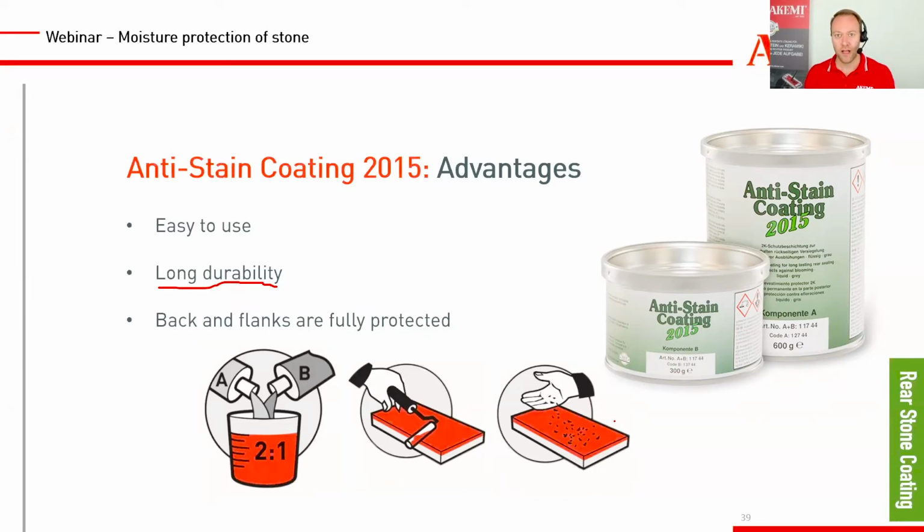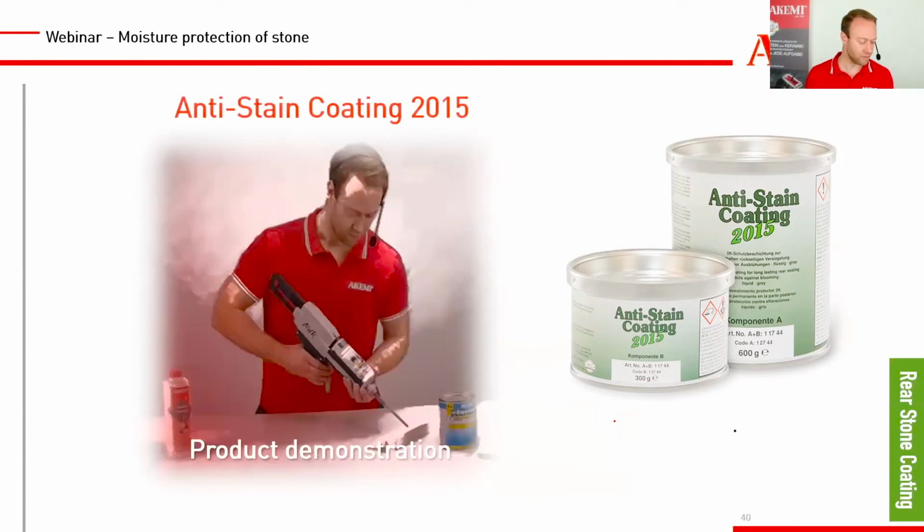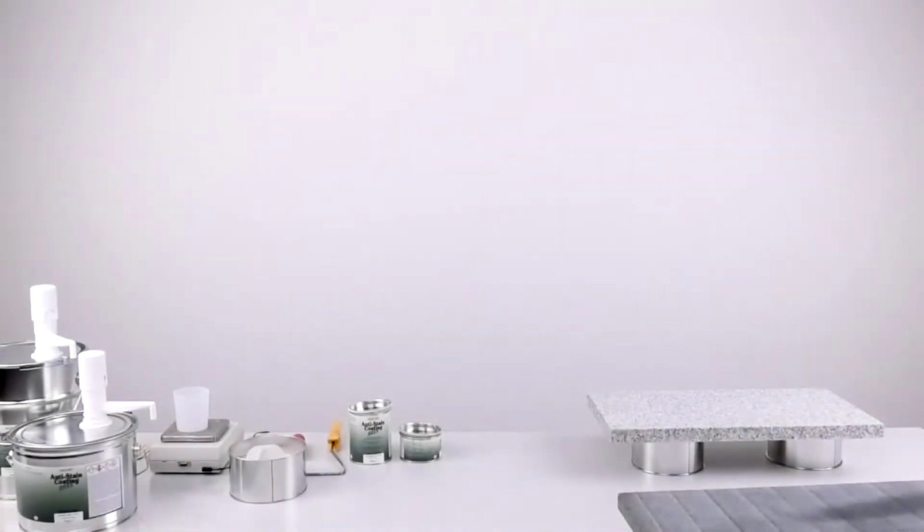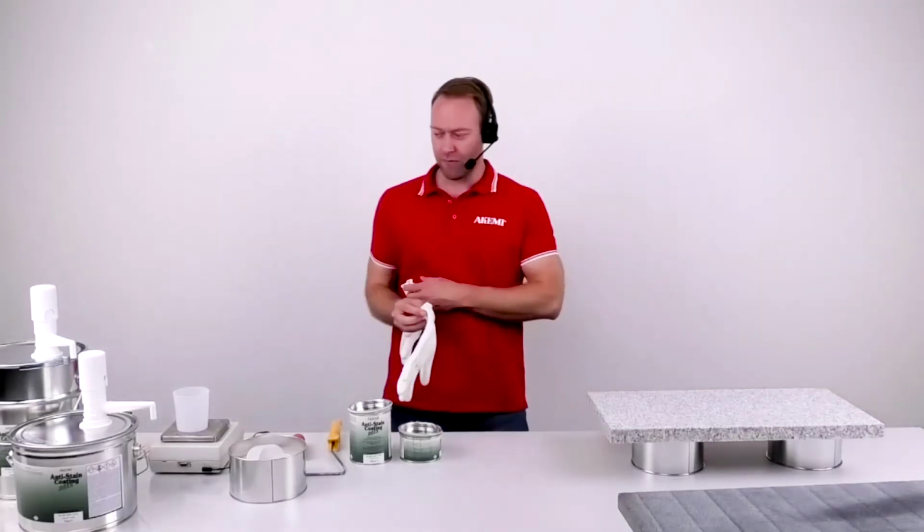And this is important because we will then have a very good adhesion to the tile glue, to the substructure. Because of course, this coating will block a tile adhesive from good adhesion to the stone. But with the quartz sand, we have an even higher adhesion to the backside of the stone. I think enough talking here. We will move there and apply it. Good.